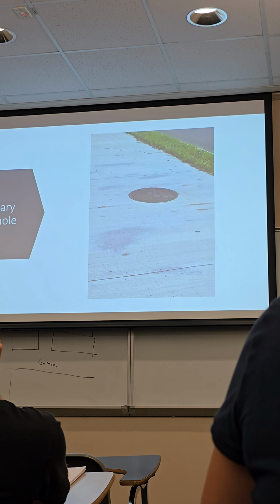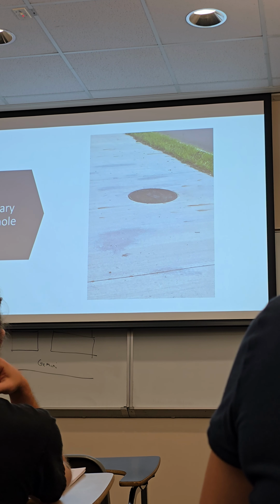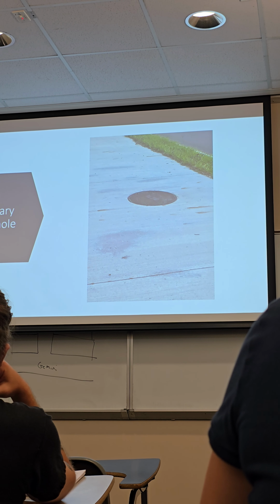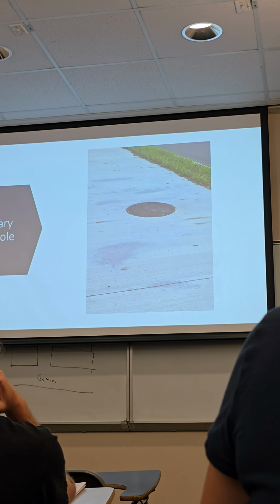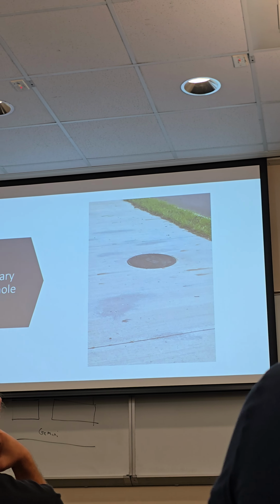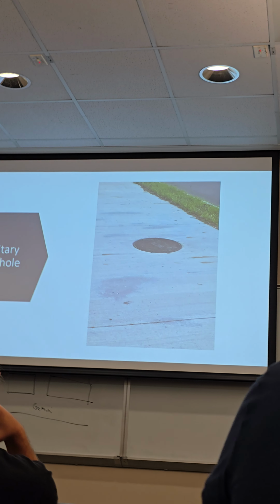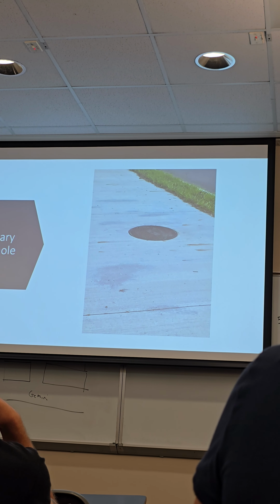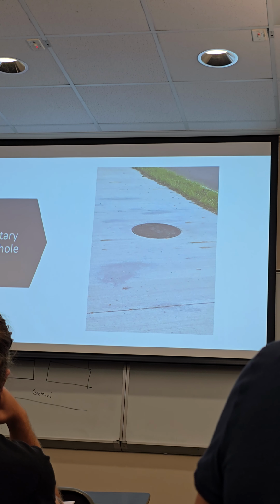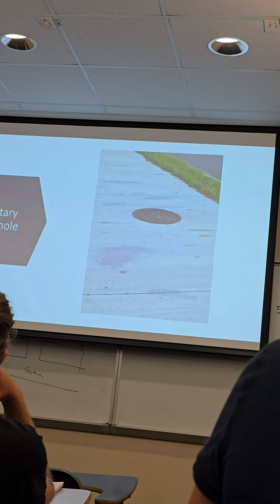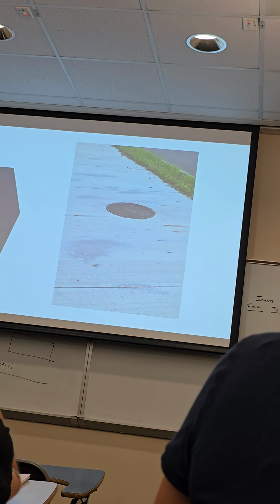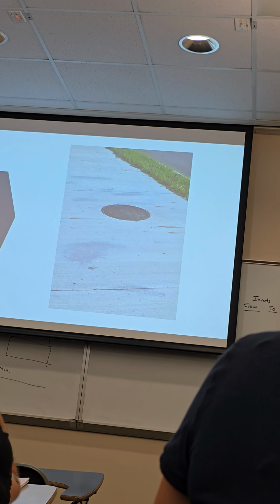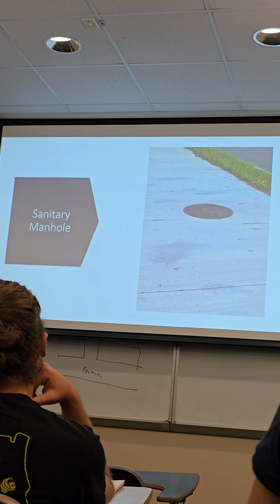So, you know, think of all the major roads, Colonial Drive, State Road 434, Red Bug, all of those. You want to try to keep that stuff out of the road if at all possible, just because people are at higher speeds, you don't want to hit that stuff. I would think more about the maintenance side because. Maintenance, that's another great point. Yeah, so if you have a manhole in the middle of State Road 436, how can you get to it? You gotta shut the road down, or shut down a lane or something. Yeah, great point. That's another very good reason to get that stuff out.